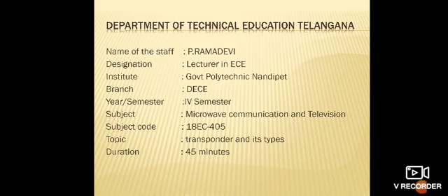So what does a transponder mean? It is a transmitter receiver combination in a satellite, so we call it a transponder. The combination of transmitter and receiver, that means it works as a transmitter and receiver in our satellite, acting as an RF repeater station. Typically communication satellites have 12 or 24 or more transponders. Not only a single transponder is used.